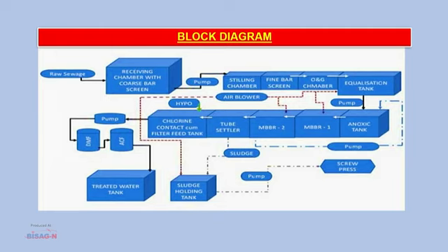Sludge feed pump. Centrifugal monoblock self-priming sludge pumps shall be used for pumping sludge to the unit. The pump shall be designed to operate satisfactorily without detrimental surges, vibration, noise or dynamic imbalance. Sludge dewatering unit. The multi-disc screw dehydrator machine is used for dewatering of sludge. The cake produced by the multi-disc screw press dehydrator can reach dry solids content as high as 18 to 25% with